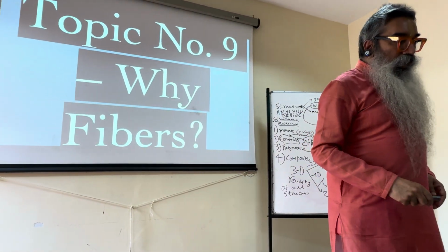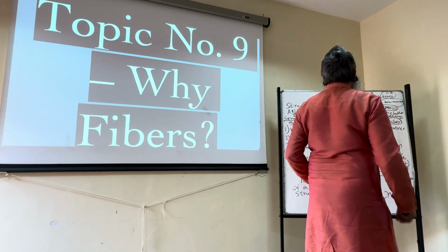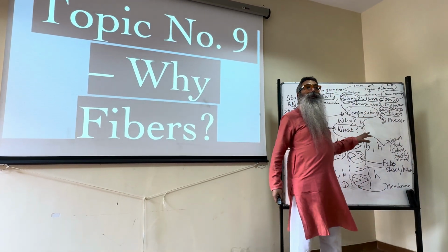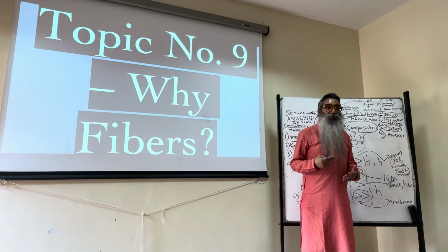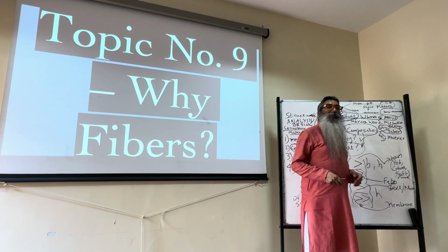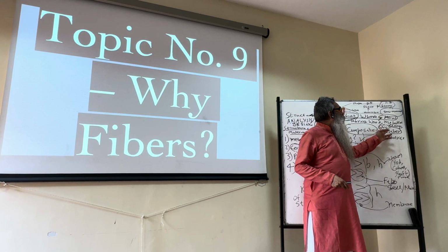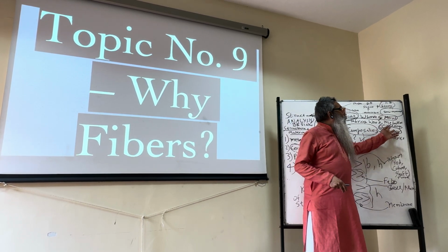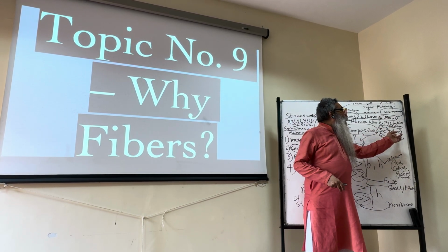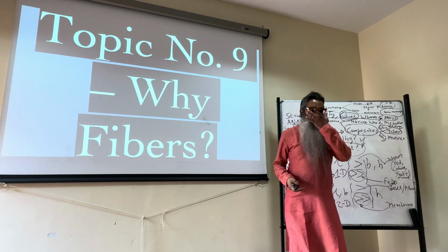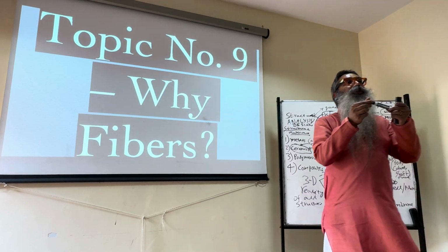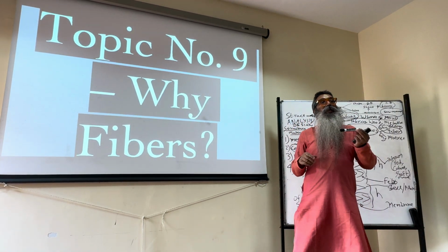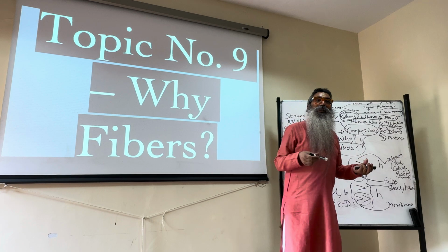So we are still answering that same question of what are composites. We already said they are made out of at least two materials, and we saw that those two main materials are the fiber and the matrix. So we took up the first of them, and we've started answering this question, why fiber. First of all, we defined what is a fiber geometry. We said that its cross-sectional dimension is small compared to the length, but just being small is not enough because that's a rod as well.